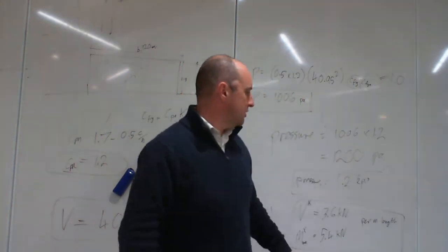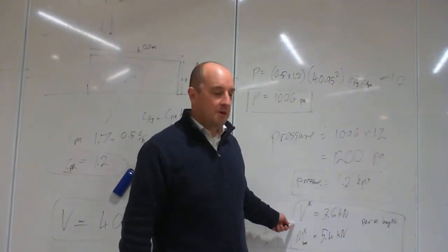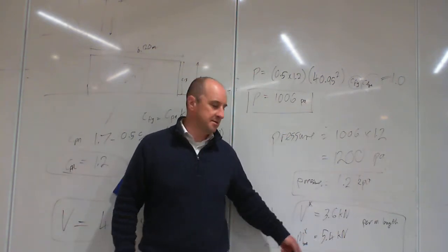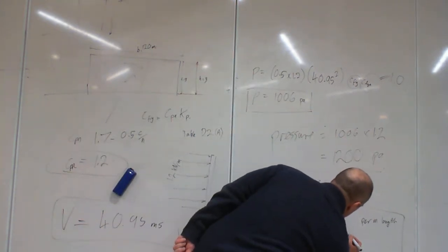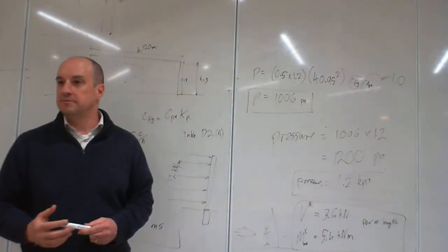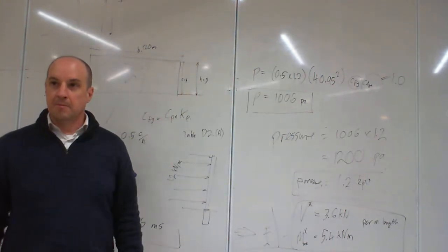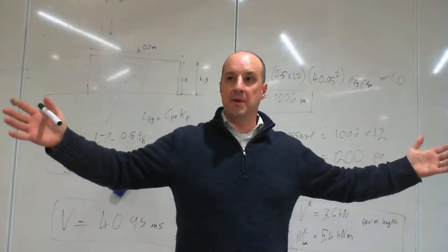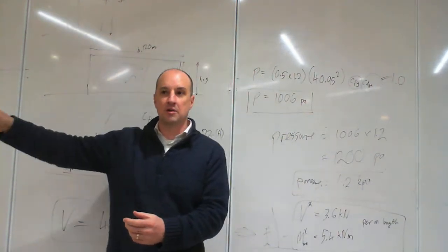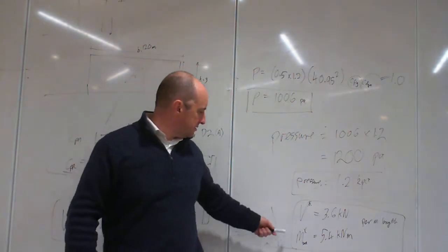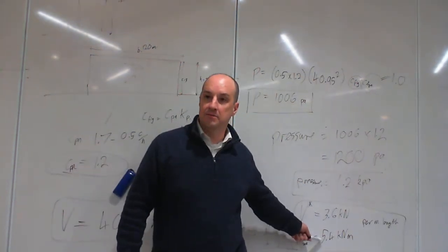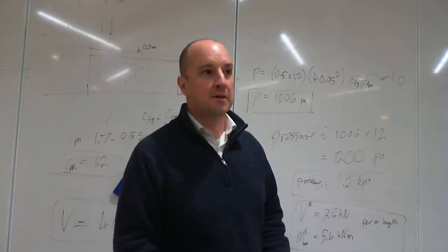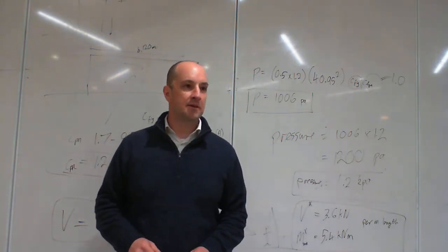Okay? So when you're designing a wall, on the footings, the bending force is 5.4 kilonewton meters per meter length of wall. All right, so if you've designed a wall which is concrete panels, which span 2 meters, and you've got steel columns in there every 2 meters, you're going to have 10.8. Okay, that's the bending force you've got to design those posts for. Does that make sense? Any questions on that?